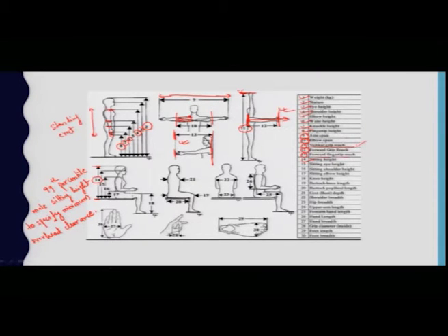And in fact, we allow about 20 millimeters if hard hats are worn. Since this person is not wearing a hat, we are not giving anything. So, as an allowance, the 99th percentile male sitting height is used to specify minimum overhead clearance. Again, number 15 is sitting eye height. That sitting eye height gives the center of the visual field of a seated worker and the maximum height of a visual display.